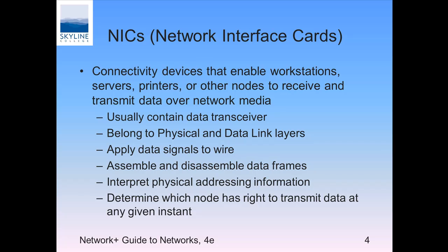With the wire, you'll use 4 wires, right? 2 pair. 2 pair were for transmitting and 2 pair were for receiving. The reason you had to do the crossover for like-to-like devices is so that when you cross the pair, the transmit signal went to the receive wire, to the receive portion of the other device itself.